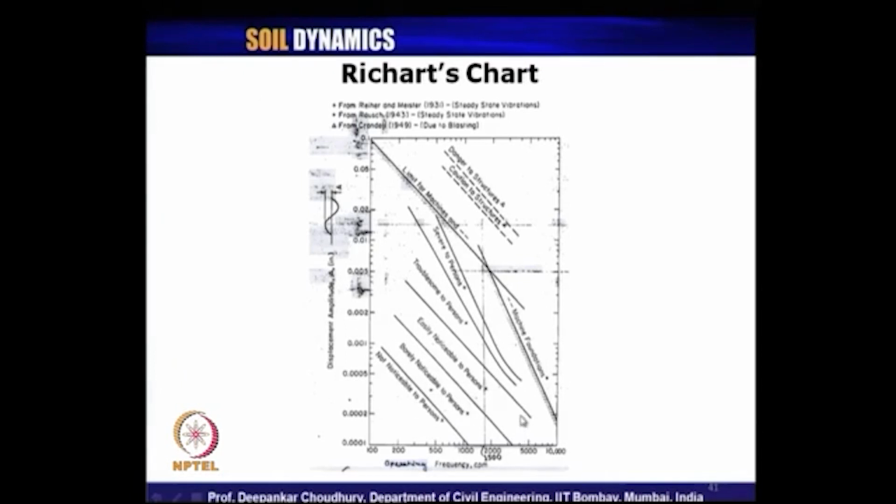That is why I said you can go up to this zone also for turbo generator. Of course, we know that power plants etcetera are not in the close vicinity of any residential area, hospital or schools, more so for their turbo generators, because of this reason. Now, this chart I have shown you is valid only for vertical mode of vibration.